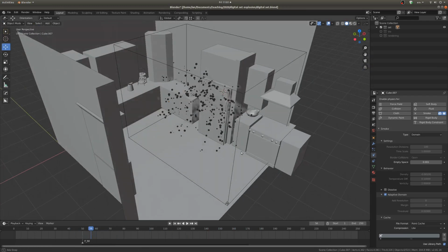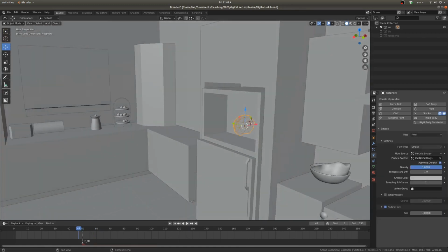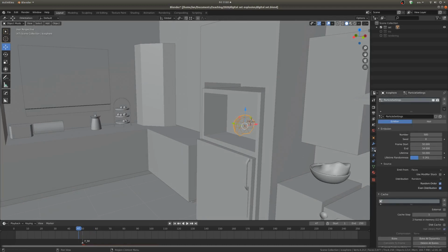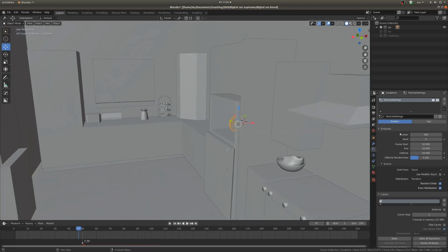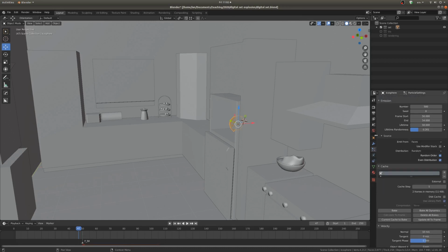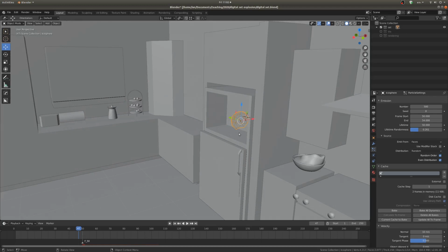So let's take a look real quick here at what's going on. There's an icosphere. I already told you about that. We've got that emitting smoke, except it's got a particle system going on. So here in the particle tab, you can see I enabled a particle system. Let me just run through the settings on this real quick. We've got about 500 particles going off, and it starts at frame 50, put a little marker here, and ends at 54, so it's a big burst, and then it's done. We've got a lifetime of 50, and I've turned up the lifetime randomness a little bit. So the source, I think this was unjittered, but I set that to random just so that it wasn't all coming out of the exact same faces and making kind of weird stuff going on.